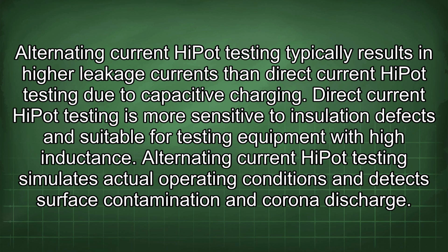Direct current HiPot testing is more sensitive to insulation defects and suitable for testing equipment with high inductance. Alternating current HiPot testing simulates actual operating conditions and detects surface contamination and corona discharge.